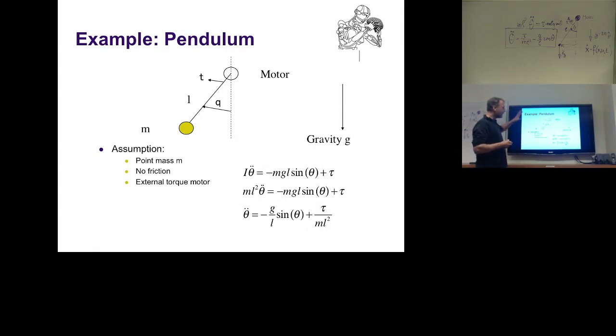Cool. So we derived, just in a very ad hoc, intuitive way, a model of a system. We haven't done any observation equations in this particular case. Observation equation would, for instance, just be that, can we write this down? If you can only observe here with a position sensor the position theta of the pendulum, well, then you could just write y equals, the complete state of the system is obviously theta and theta dot. This is the complete state.